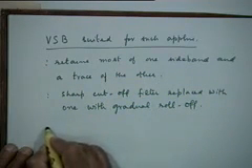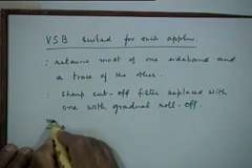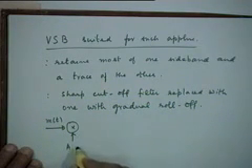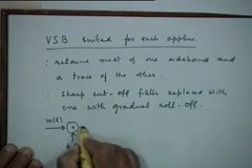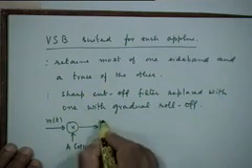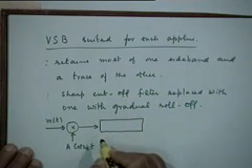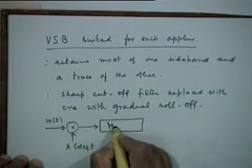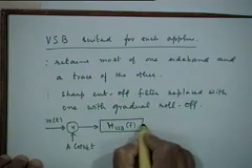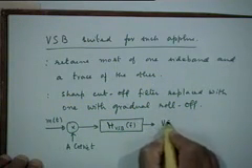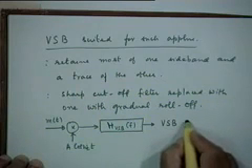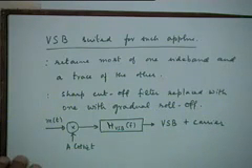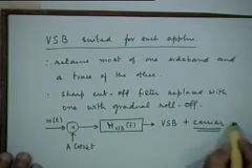So what we are saying can be pictorially expressed like this. You generate your message signal, you do DSB-SC modulation on this by multiplying this with A cosine omega C t, and you have a sideband filter here, but it is not that sharp cutoff filter. We will call it some H sub VSB of f, which will yield the VSB signal. Typically, if required, you may also send some portion of the carrier, but that's not important right now.